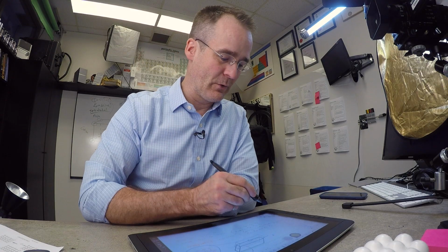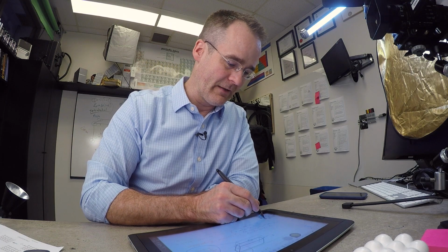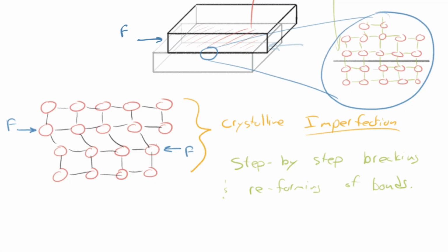And now that we understand that, the beauty of this is that it's only good if you can apply it. But now that we understand this, there's so many things we could do. What if I put a carbon atom into the lattice like that, and it's going to interact with that movement? Is it going to make it harder? It's going to make it easier. Well, sometimes it's going to make it harder. It could make it stronger. That's the mechanism for alloying.